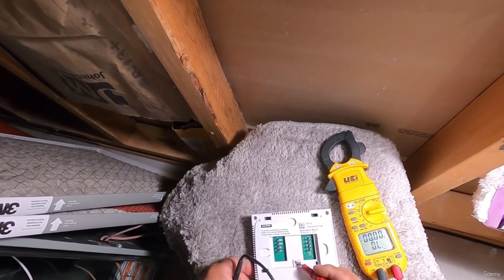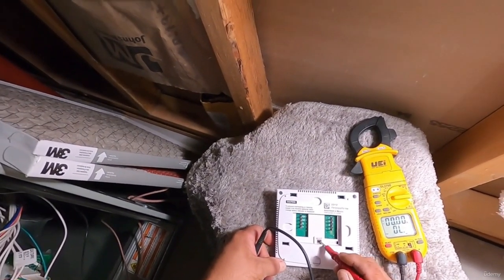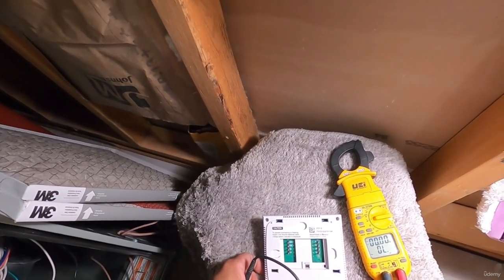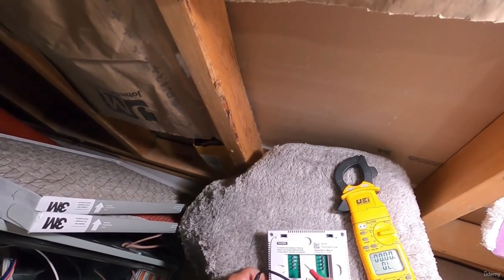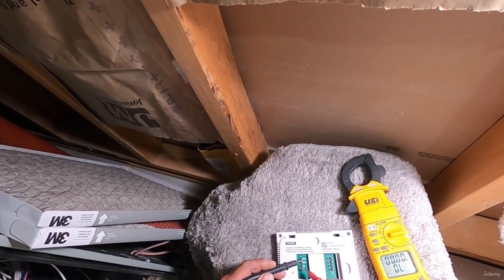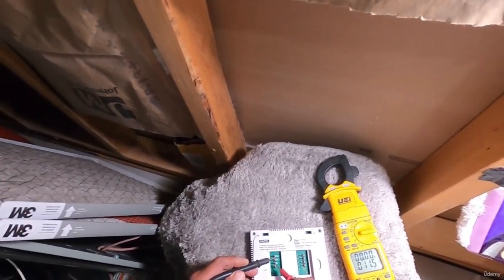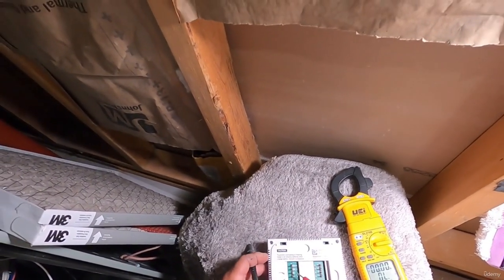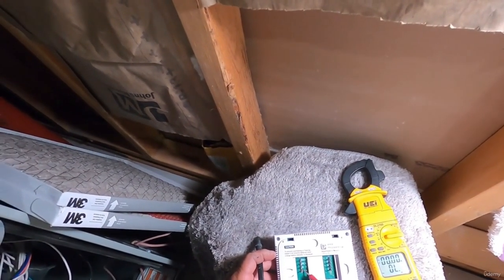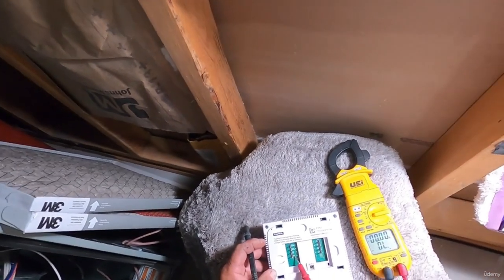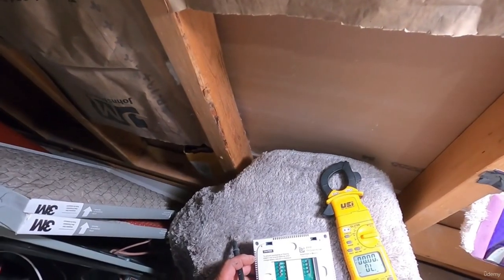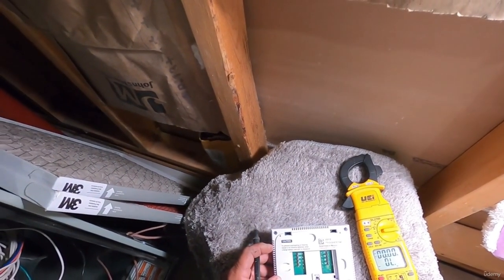Down here you have a little switch for gas or electric, depending on what your furnace is. If you got an electric heat pump or electric heat strips, you'll switch this to electric. If you got a gas furnace, you'll switch that to gas. So that's how you tell if your thermostat is working. You pull it off the wall, set it to cool, and you should have continuity. In other words, it's making internal contact from the red to the yellow to send power down to the yellow on the terminal board, on the control board. So again, if you're not getting continuity, then your thermostat is bad. And that's how we read the thermostat.